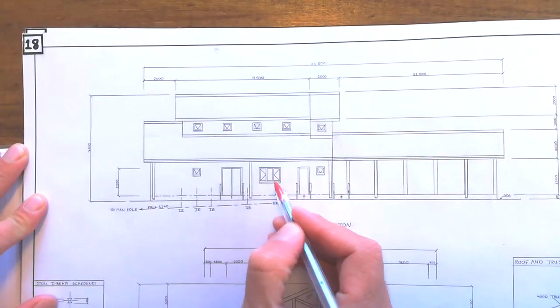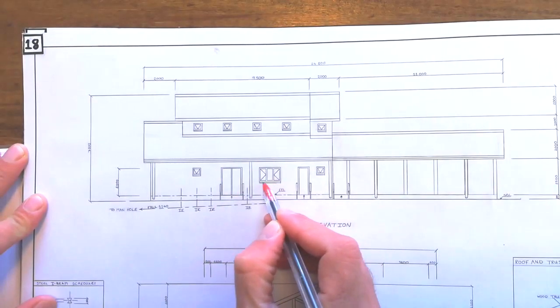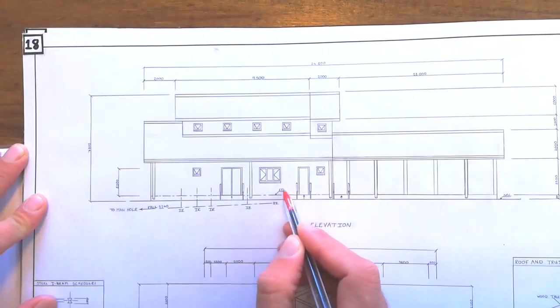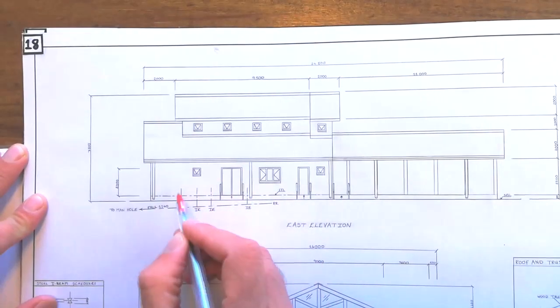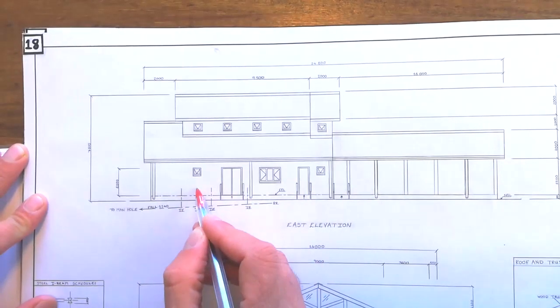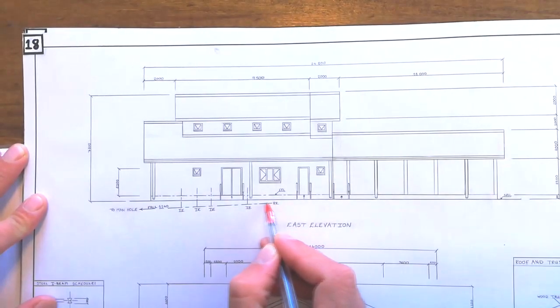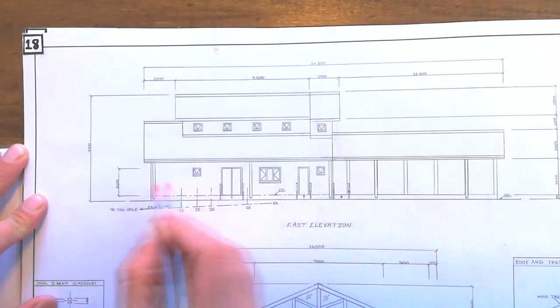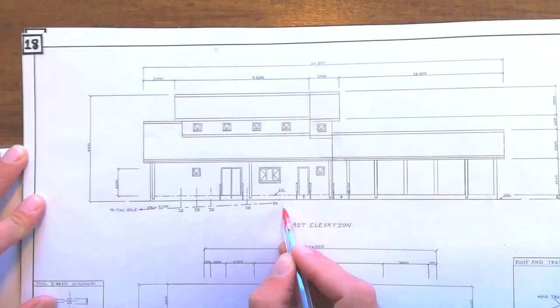They've got their windows in here with their doors, the door frames clearly shown, with your window sills, the opening of the windows, that's going to be important. On the outside, your finished floor level. And then this is a bathroom area here, so you can see there the sewer pipes coming out of the bathrooms into the inspection eyes, with your main sewer line with a fall. This is the type of detail when they ask for your sewer detail on your elevation.